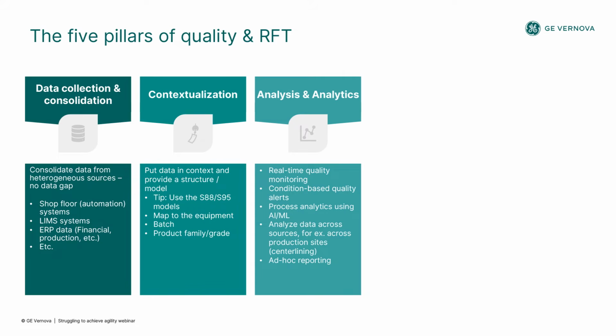Again, the ability to apply simple analytics like SPC, where, say, 3 points out of 5 are above warning, so you know you might be coming into a problem. That's really helpful to know. Now you can get into deep stuff like artificial intelligence and machine learning, which are some of the things that we're working on at GE Digital, and the ability to let the system tell you what's happening and why it's happening. One analytic that we're working on tries to predict the downtime reason based on various variables into that equation to understand really what the downtime reasons are.